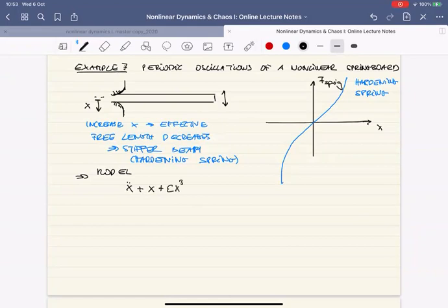spring here, right? And I have put the epsilon there because this effect is still tiny. So when I really want to work out what's happening here, that will be tiny. That means the spring force will be x, again after non-dimensionalization, plus epsilon times x cubed. So this is a fairly mild effect. Nevertheless, it does make the system nonlinear.